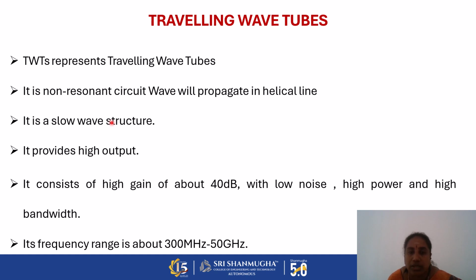Compared to the reflex klystron, it provides high output power. The maximum gain of the traveling wave tube is up to 40 decibels. With low noise, we always generate high power output, and based on the frequency ranges, the bandwidth is also very high in traveling wave tubes.